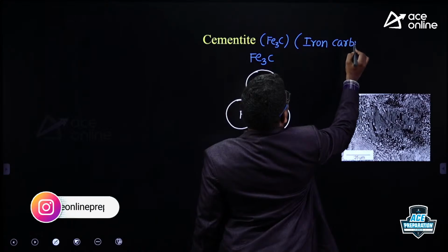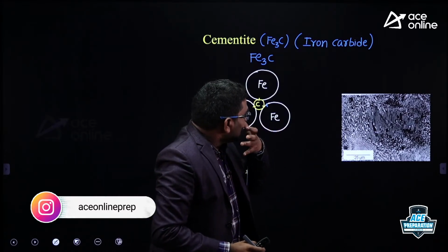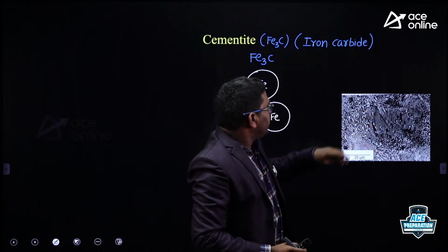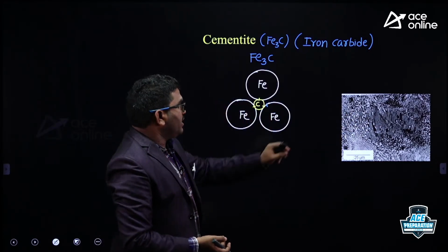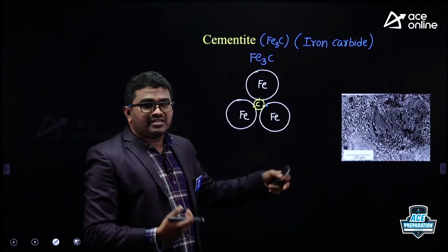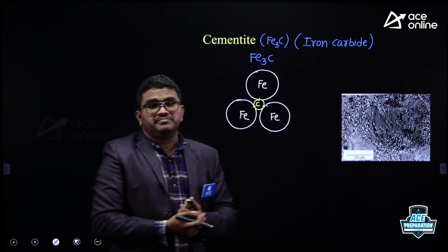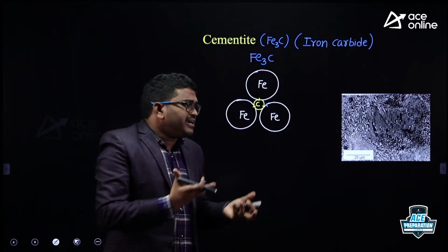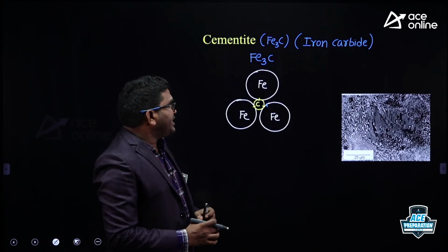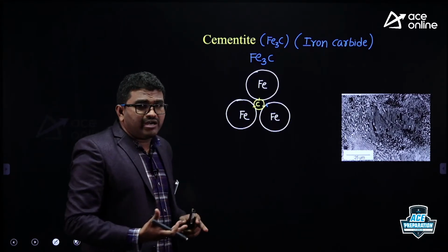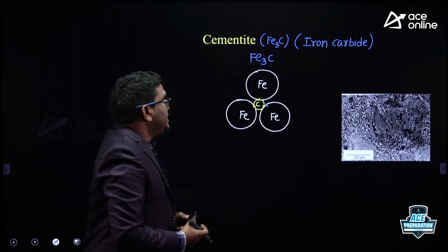Iron carbide. Okay. So, the microstructure of the cementite at 25 micrometer magnification, see, this is the cementite microstructure. Thin lamellar forms of cementite are present. Surrounded by that there is ferrite, it is a pearlite structure actually. That black color one represents cementite. So, what is cementite? Cementite is one phase of iron carbon alloy. Cementite is formed by strong covalent bonds. So, it is a hard material, high strength material, okay, hard and high strength material.